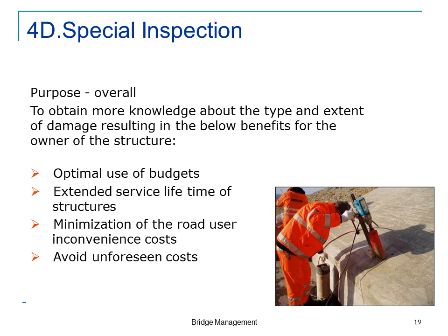And it's also often possible to postpone the repair if you know what is going on, because it might look bad and turn out to be no problem. The purpose of all these things is to spend the money in the best possible way, to extend the service life, and to minimize road user costs and inconvenience. And yes, it is to avoid unforeseen costs.